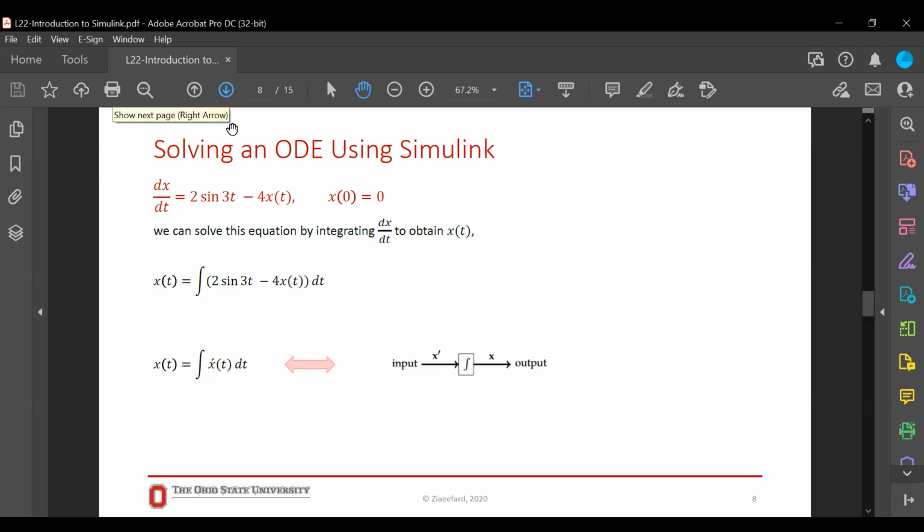No, it isn't. Remember, for a differential equation, you had to look at the coefficient. If it was just a constant number value, it was linear. If the coefficient was a function of the state, for example, sine of x times x of t, then it becomes nonlinear, right? So right now, our state is x of t. So -4 is a constant value.